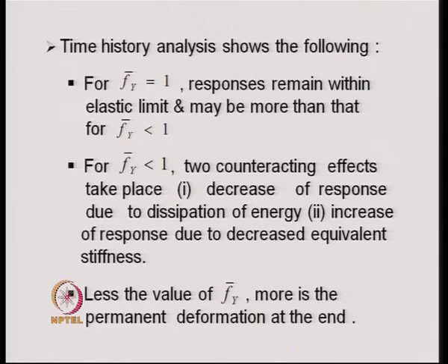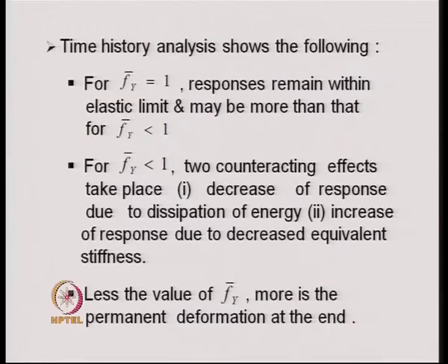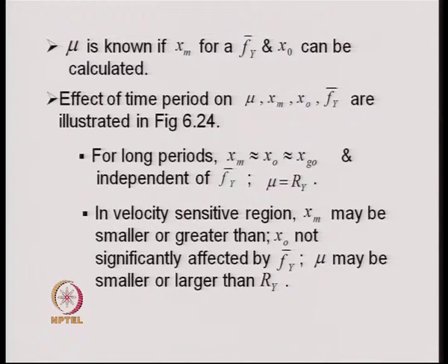That is obvious because the more value of f bar y means that the system is having more inelastic effect. Therefore, at the end of the earthquake episode, we observed that the system has undergone some permanent deformation, element-wise as well as overall structure.